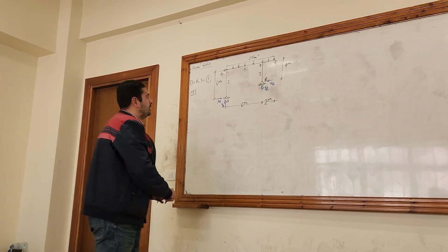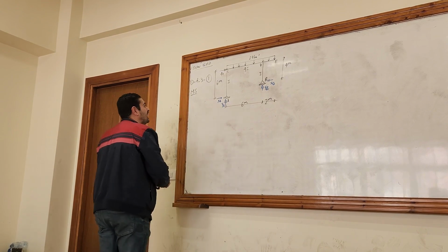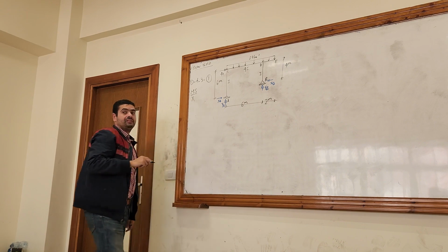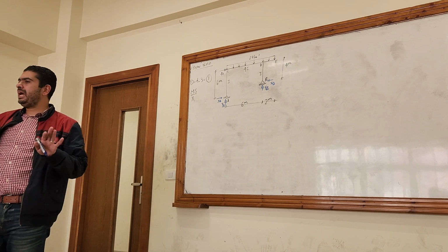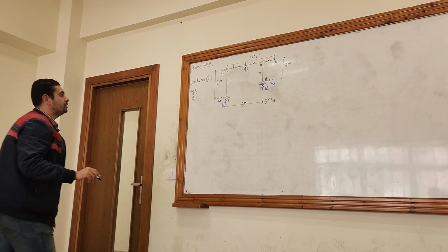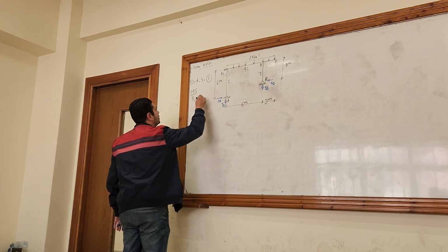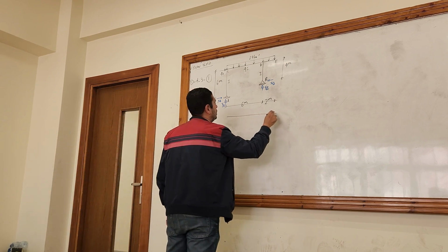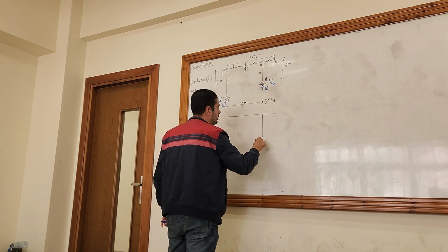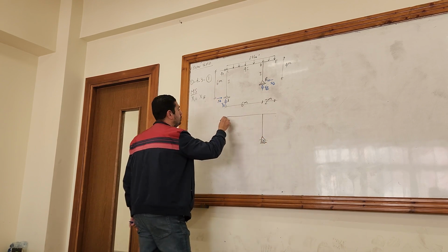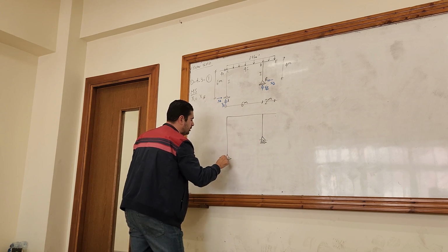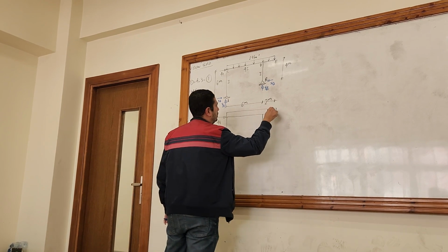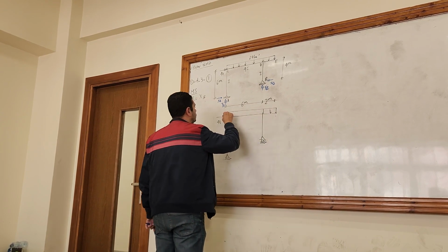Let's make the hinged support at B a roller support, so the redundant that I will remove, that I name X, the same as in superposition, will be XB. Right? So the main system will look like this. The hinged support here was converted to a roller support, and then the same loads like this.